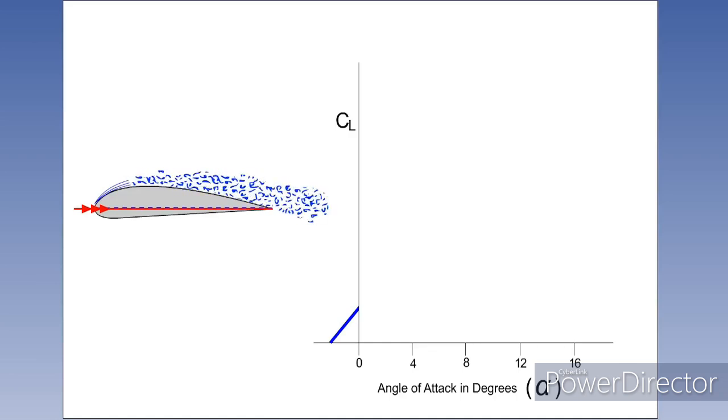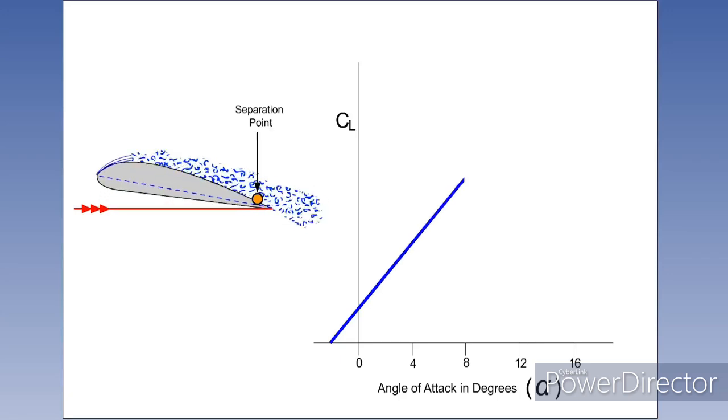Since the CL max of an aerofoil corresponds to the minimum steady level flight speed, the 1G stall speed, it is an important point of reference. The stall, then, is caused by airflow separation, which occurs either when the boundary layer has insufficient energy or the adverse pressure gradient becomes too great.